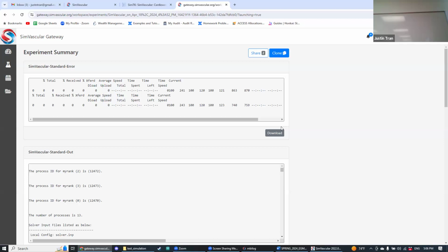Even with the smooth, it's not. Like this part right here, it almost looks like the model's kind of like. Actually, let me try this. Before that, you can try some of the other smoothing operations too. The constrained one is the most conservative, but all the other ones are more aggressive. Decimate is a pretty aggressive one. What that aims to do is eliminate some of these surface intersects. This didn't exist before. Oh, it's actually really good.